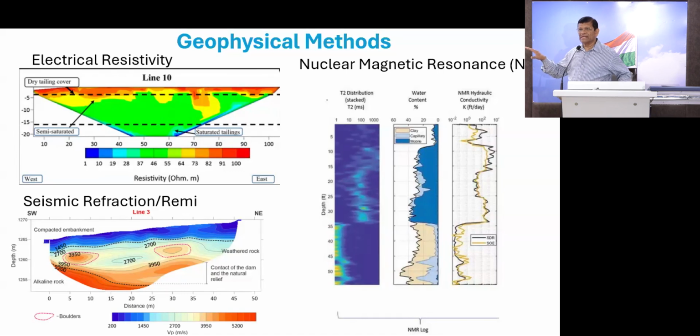Again, the electrical resistivity works very well if you really have a saturated zone there, like a phreatic water table. Most of the tailings I have worked in were in a very dry climate. In the dry climate, these tailings have water in them, but there is no phreatic surface developed there. There are perched waters, like I call them, water pockets. But it's very difficult to find those water pockets using the electrical resistivity method.